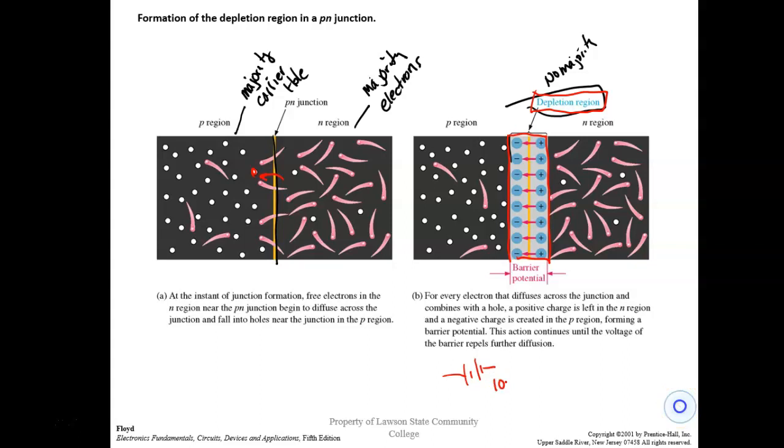So that means if this guy puts out 10 milliamps maximum, then what the meter does is it automatically raises its voltage up to put out 10 milliamps through the resistance. And 10 milliamps means it can display that up there, turn on a dot somewhere and put ohms over here, right? You understand that? And this is why if you put an ohm meter into a live circuit, you can damage your meter because you're going to be pushing current back through your source, right? So be real careful on that.